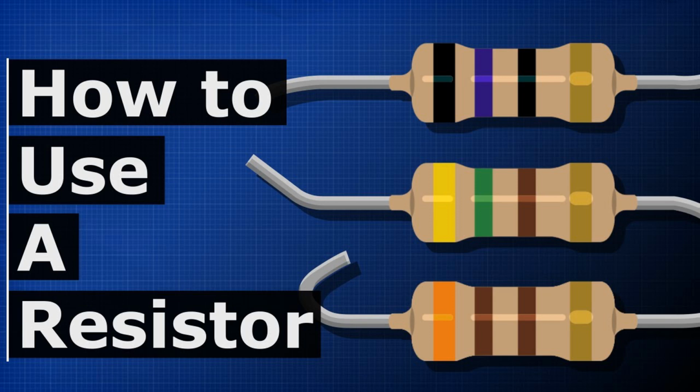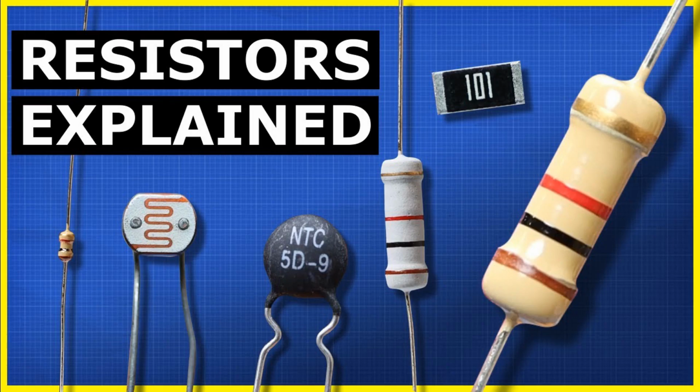Voltage noise, also known as Johnson-Nyquist noise or thermal noise, is caused by the random motion of charge carriers, usually electrons, within the resistor due to thermal energy. This motion creates tiny voltage fluctuations across the resistor. Voltage noise is typically described in terms of its root mean square, RMS, value, and is proportional to the square root of the resistor's temperature, in Kelvin, and its resistance value.